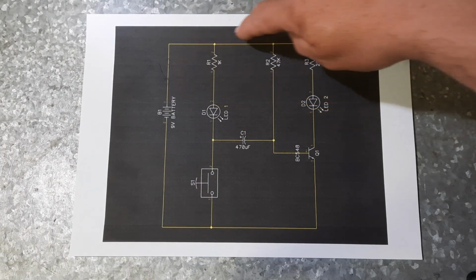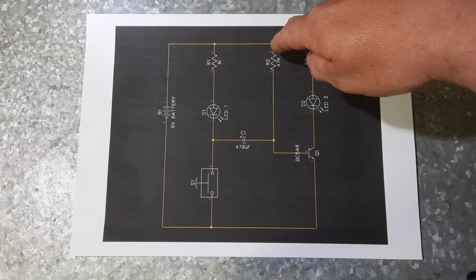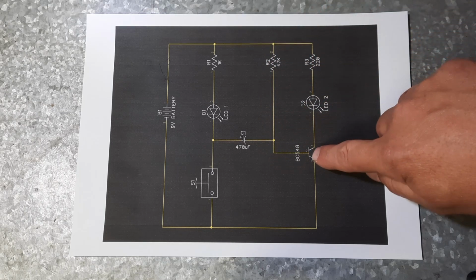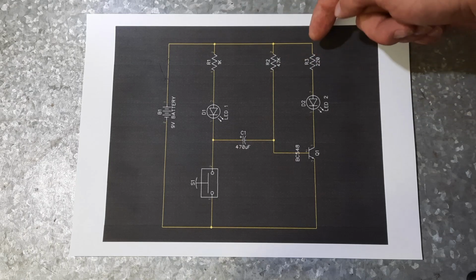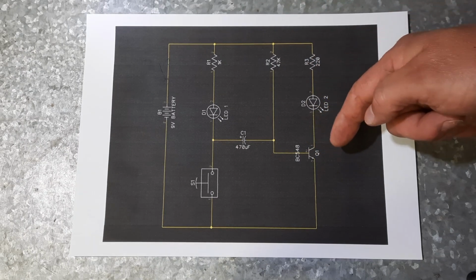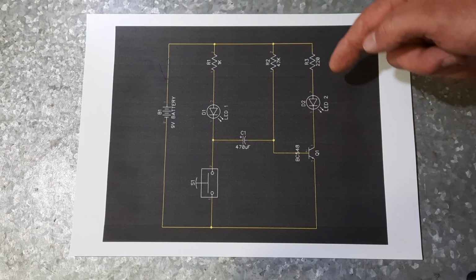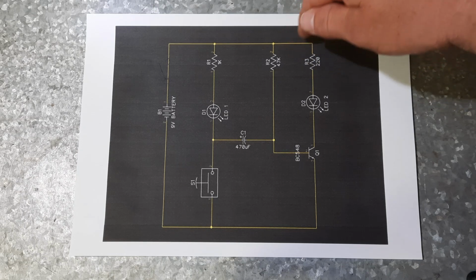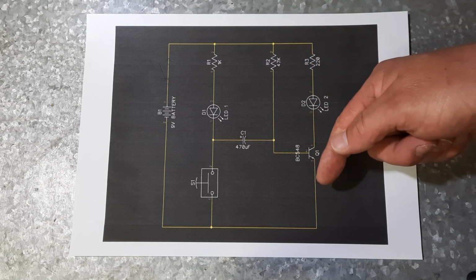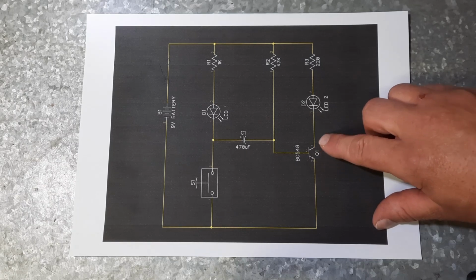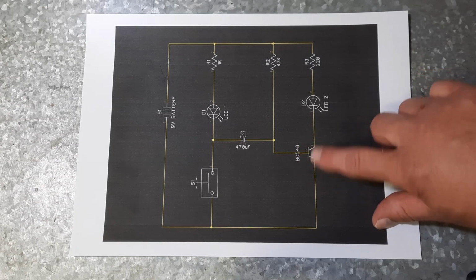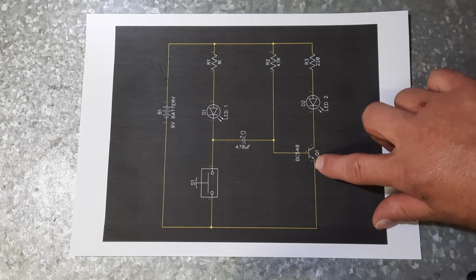So power is going to flow from here down to here through the base of this. It's going to flow from here down here, conventional current. I'm not going to talk about non-conventional current, it's too confusing. So power will flow down through here, and this transistor will turn on. So imagine this as on. Straight bit of wire from here to here.